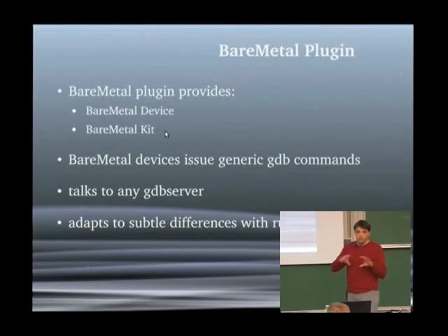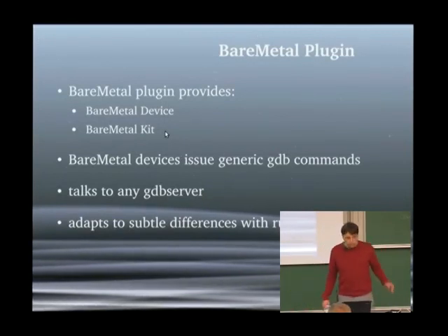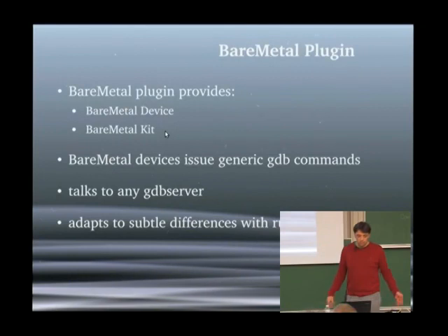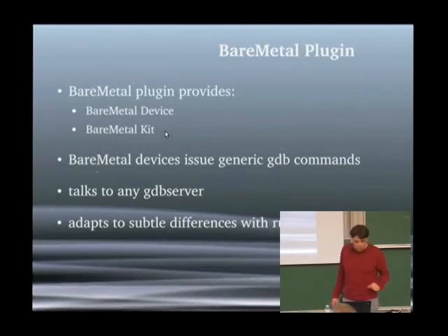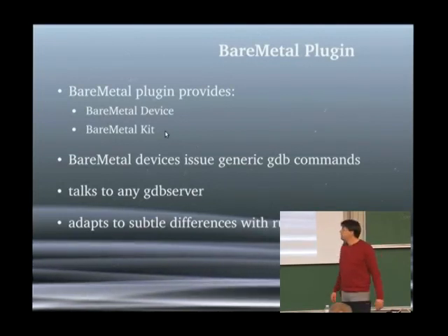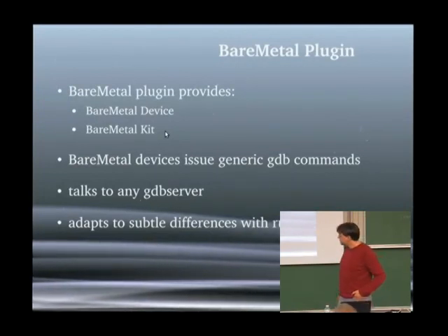And it has a window where you can type in your GDB commands, which is pretty basic but very versatile, because every hardware debugger I used, besides OpenOCD, which are commercial ones, can also be used with this BareMetal plugin.